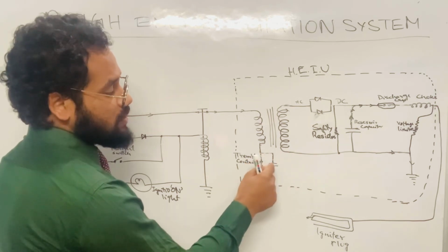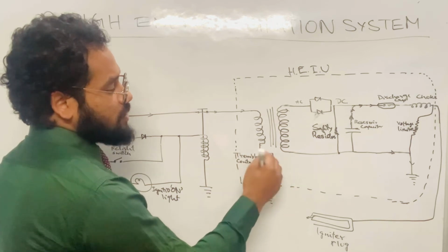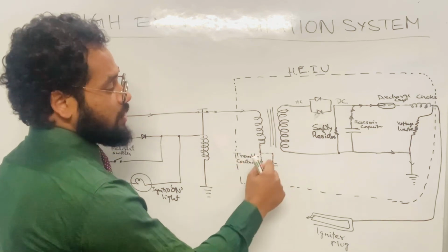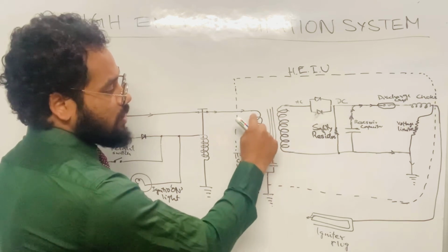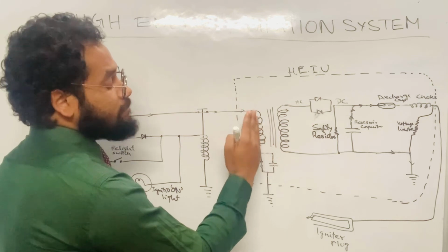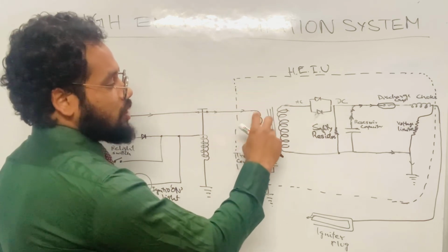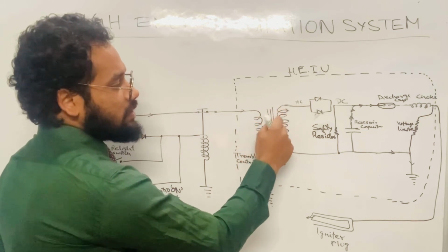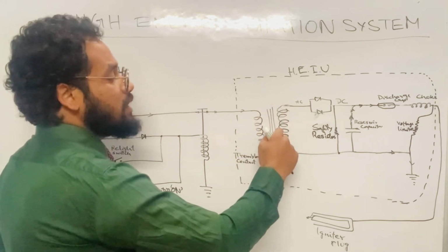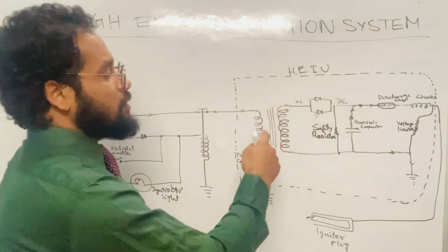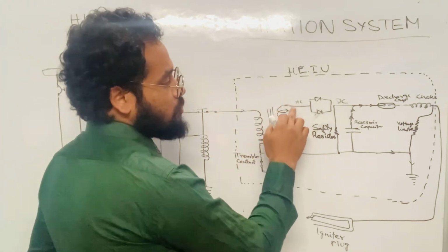So we have discussed that the capacitor will repeatedly charge and discharge, and have these cycles of charging and discharging repeatedly, because of which there will be a fluctuating current in this induction coil, and that current will produce a fluctuating or moving magnetic field. That moving magnetic field will cut these stationary secondary conductors and cause an EMF to be induced in it, a very high voltage EMF, and that high voltage will obviously be AC.